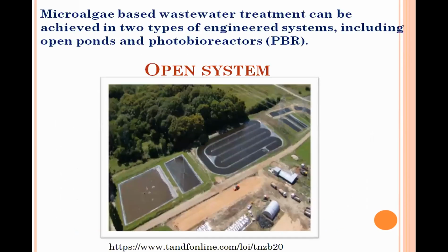So now researchers are thinking about using microalgae to treat wastewater. And yesterday we had a speech from Dr. Saad representing the open system and how we used the open system for treating wastewater. However, this is an effective method for treating the wastewater via the facultative pond followed by the high rate algal pond. But this process needs or occupies a big land footprint.